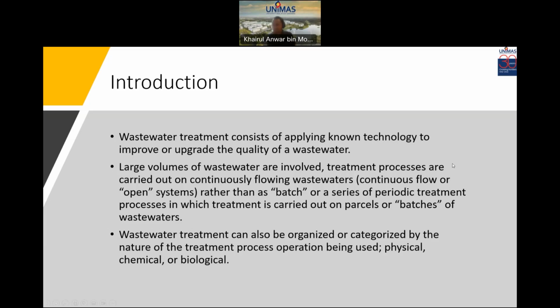Wastewater treatment consists of applying knowledge and technology to improve or upgrade the quality of wastewater. Large volumes of wastewater are involved. The treatment processes are carried out on continuously flowing wastewater, a continuous flow or open system, rather than a batch or series of periodic treatment processes in which treatment is carried out on parcels or batches of wastewater.